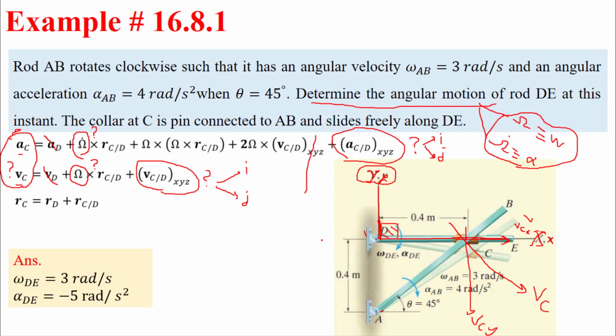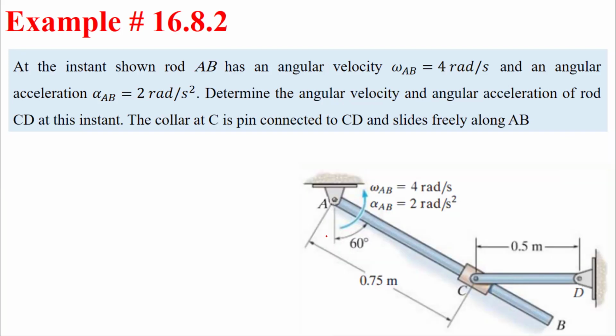You do not understand? Let us see another example. This one, for example. We'll come to it actually, but in order to explain what I mean, the slider slides on which link? DC or AB? Of course, it will slide on link AB. So I need to choose the location of the coordinate system. So I will choose the x-axis to follow AB, primary and secondary.